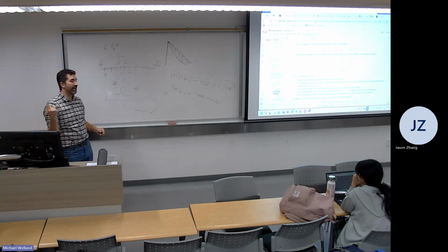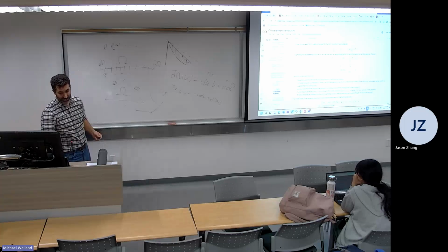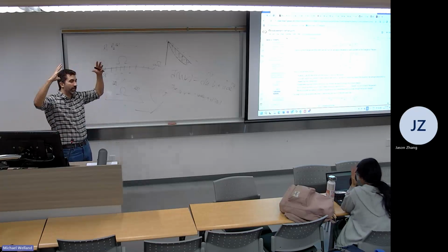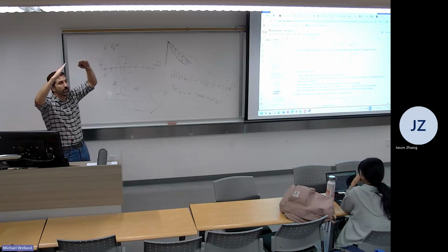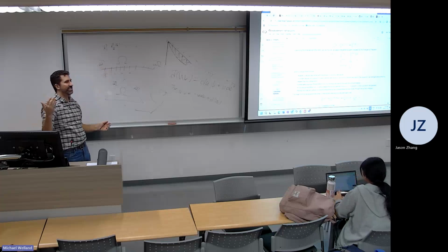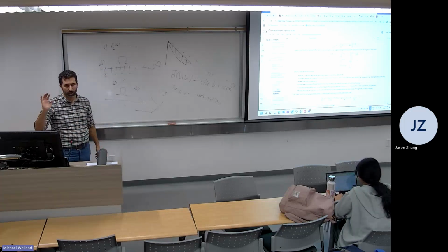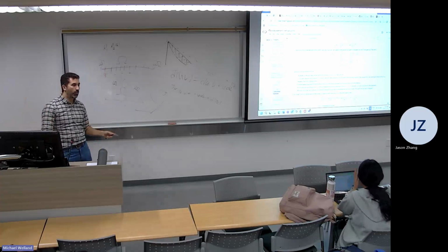Finite volume had the advantage that we're actually explicitly putting in the boundary conditions, and this one has the same thing, which is nice because what that means is that the boundary flux only can be completely localized to the boundary of your system. It doesn't impinge on the inside at all, which is a more pure way to handle that. But it also opens the avenue.